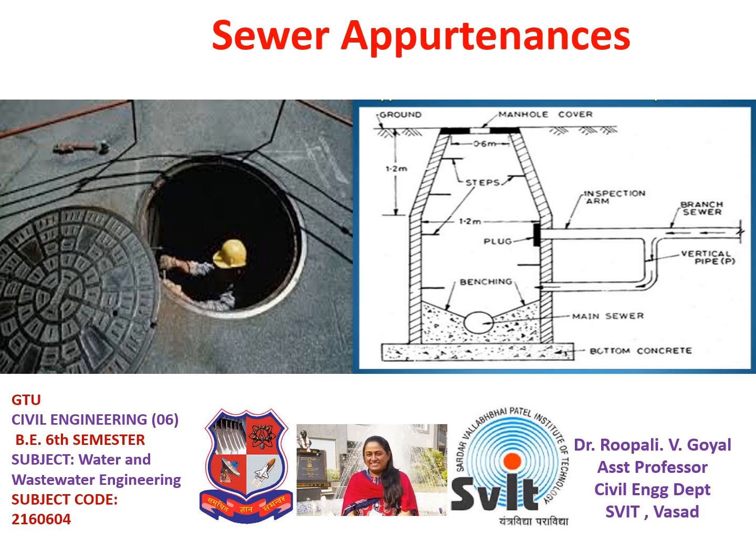Now you know the sewerage system. The sewerage system is the collection system that collects wastewater from your home, from your lateral to submain to main to the outfall sewer, which discharges wastewater to the wastewater treatment plant. All the system used for the collection and conveyance of wastewater from your home to the wastewater treatment plant is called the sewerage system.